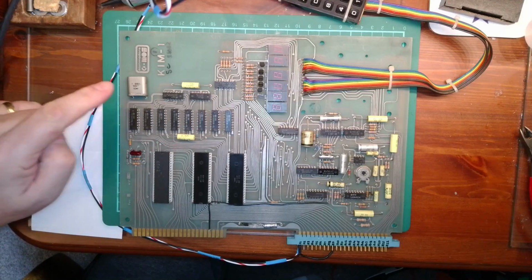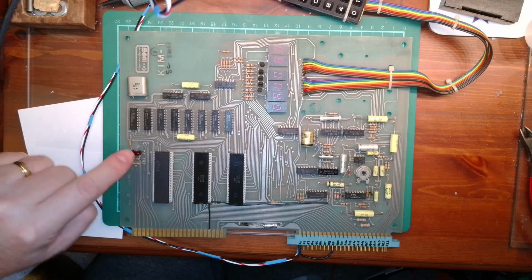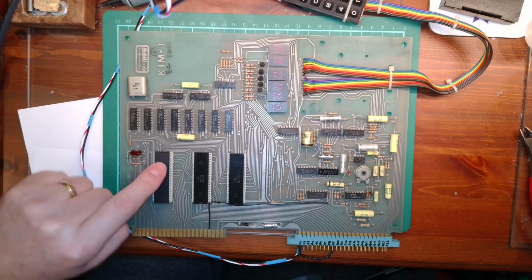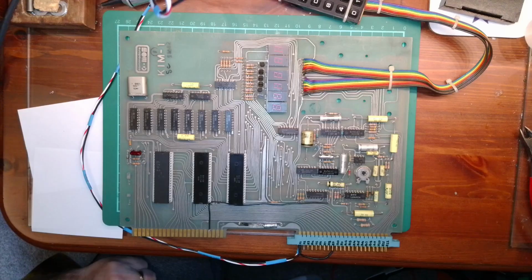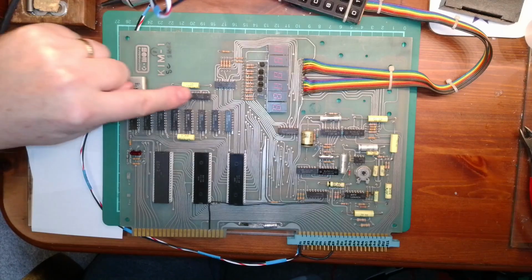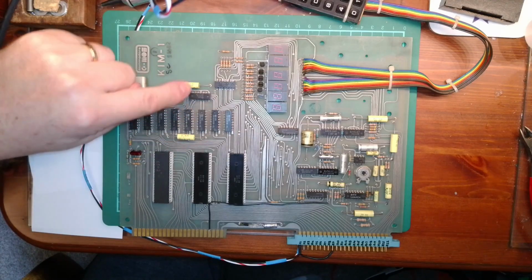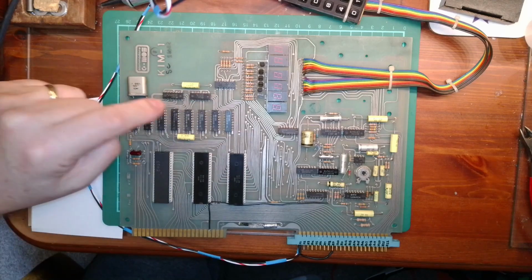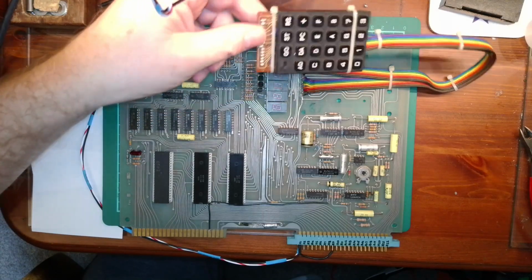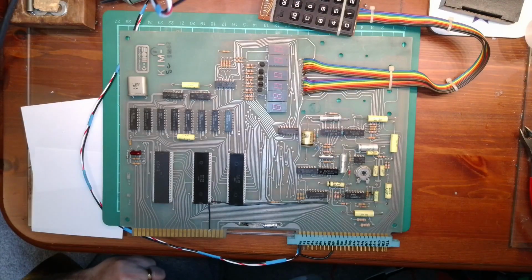There's your oscillator. You only need the crystal with the 6502 and a few other little components there. The actual clock part is done in the 6502, giving you phase 1 and phase 2 clocks out of the processor. So the output from the static RAM goes to these ICs. The inputs of the RAM are connected to the bus all the time, but the outputs go through these buffers, feeding back round. And you've got a display over here and a keyboard. The keyboard on this one's been extended out. I'm going to take all that off and mount it back on the board as it should be.